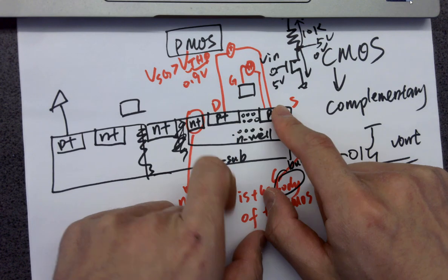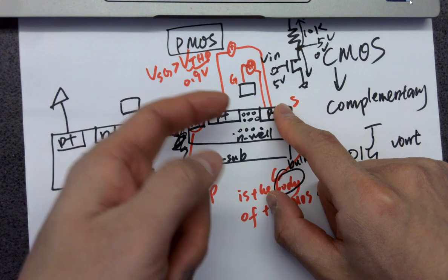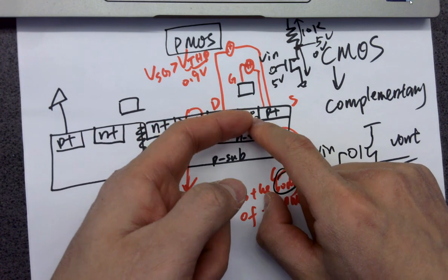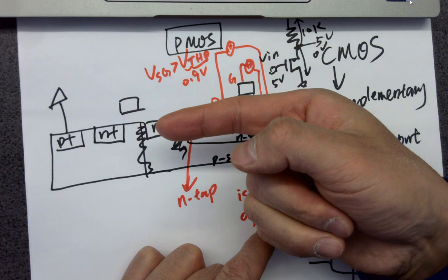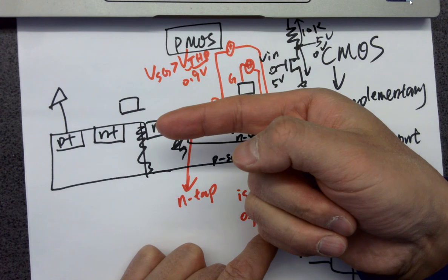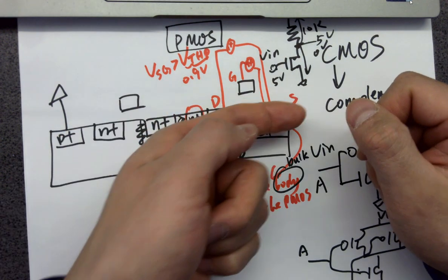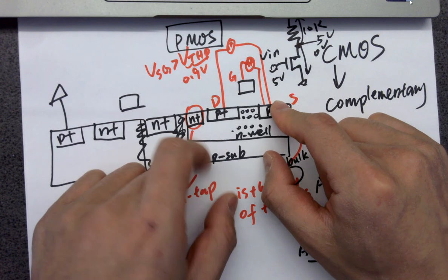High, right? Which means the electrons are going to move in that direction. So electrons moving in that direction are filling up the holes over here, and it seems like the holes are moving in the other direction, carrying positive charges. Whenever electrons move in this direction because of the electric field, we have a battery here, so the anode is definitely going to attract electrons.